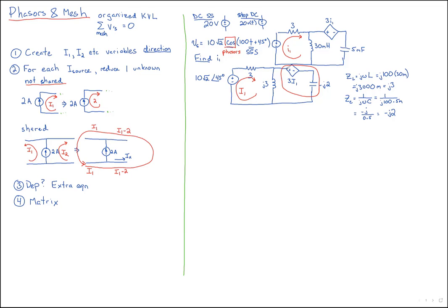Well, so here's the problem. Things are neither all in series nor all in parallel. If we could source transform this, everything to the right of this would become all in parallel. Meanwhile, if we source transformed this too, then we'd have a pure parallel circuit and we'd be done. We could just use a simple current divider relationship and walk away. So is that allowable? Can we source transform the left?